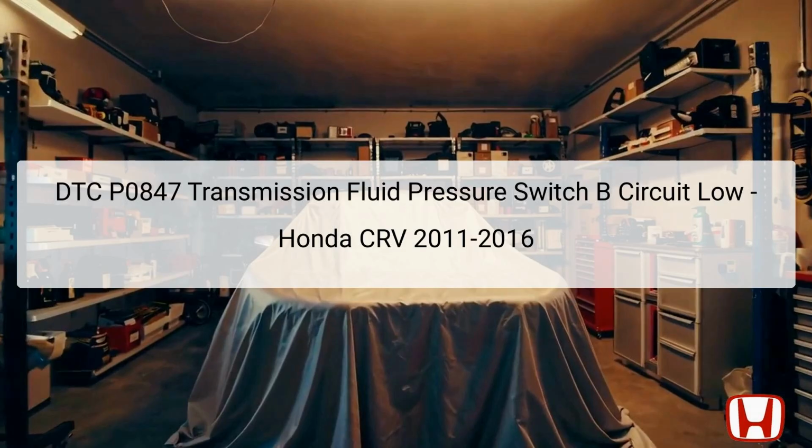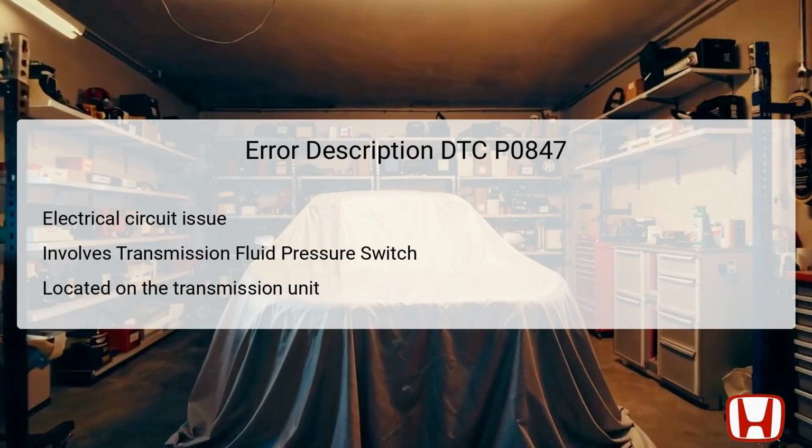the issue effectively. The DTC P0847 indicates a fault in an electrical circuit associated with the transmission fluid pressure switch B, specifically for the third clutch. A critical feature of this switch is to relay information regarding hydraulic pressure levels to the PCM, which is essential for the successful operation of the automatic transmission.